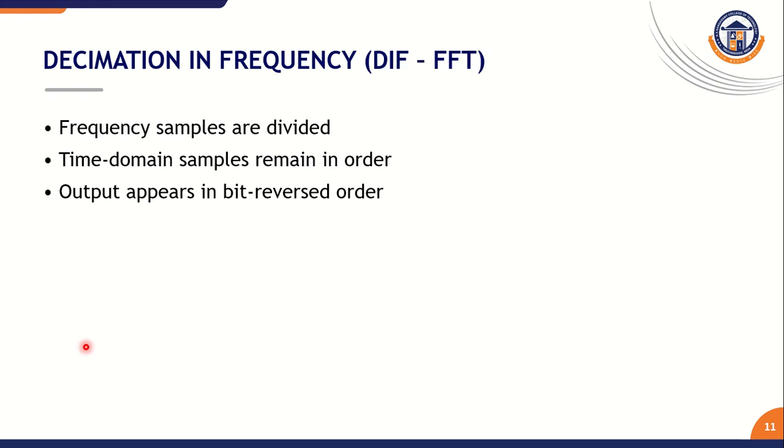What do you mean by decimation in frequency? Before, we discussed decimation in time FFT. This slide shows the concept of decimation in frequency FFT. In decimation in frequency FFT, the frequency samples are divided instead of time samples. The input sequence remains in order, but the output appears in bit reversed order. This is the main concept of DIF FFT.